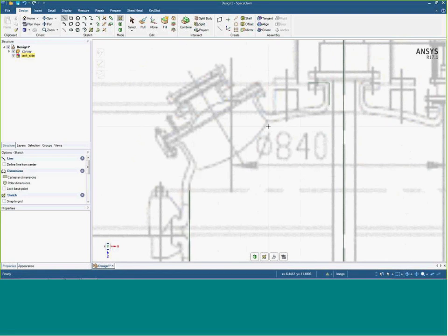Now this profile that is going to curve through here, I'm going to kind of eyeball it with a spline. So there's a spline feature. If you move the mouse close to the endpoint, then it can snap to the edge of this line. If I hold the Alt key on the keyboard, then it will put a couple parallel lines to make this tangent. So now I'll click that, and this spline will come off tangent. And I just want to kind of get this edge through here to match up. So maybe somewhere about there gives it kind of close to matching up. Maybe click here and click here. Once I'm done with this, then I can just hit the escape key to complete that operation.